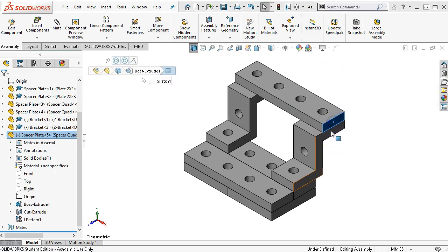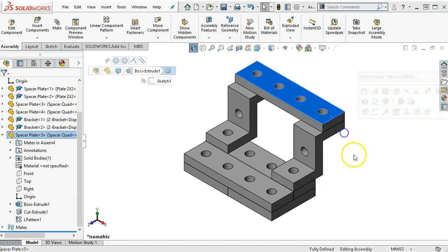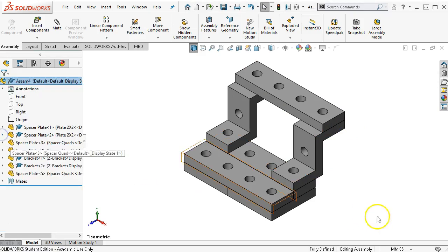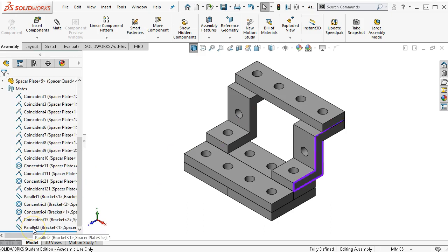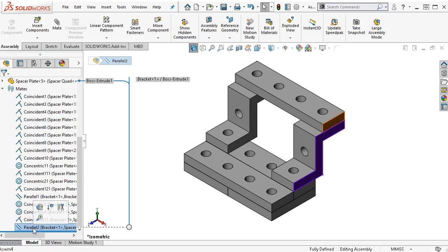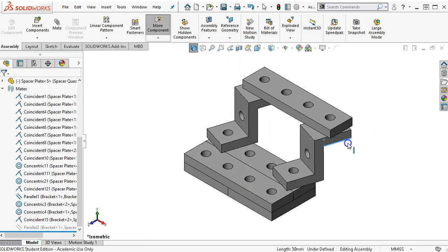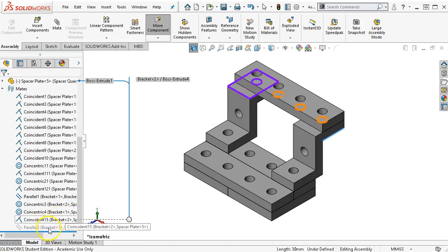So if I was to make the ends coincident or parallel, that would cause it to become fixed or fully defined. Alright, that would bring it into position. So these are decisions you have to make about the results. Even with the edges, if I'd brought that edge and that edge coincident, it would have had the same result, except I still wouldn't have been able to see the rotation. At least now, if I wanted this to be dynamic or needed it to be, the parallels are easy to identify. And if I suppress one of those parallels, I can very easily get back to its dynamic situation.